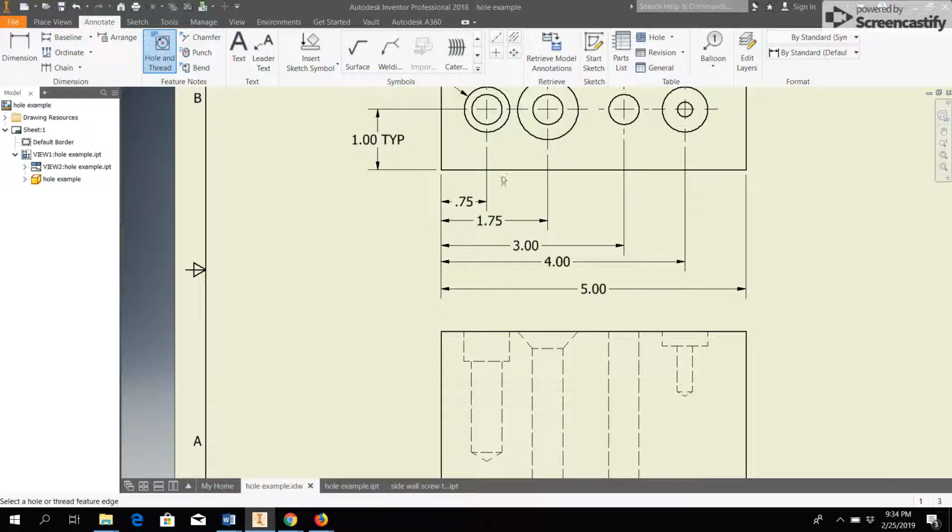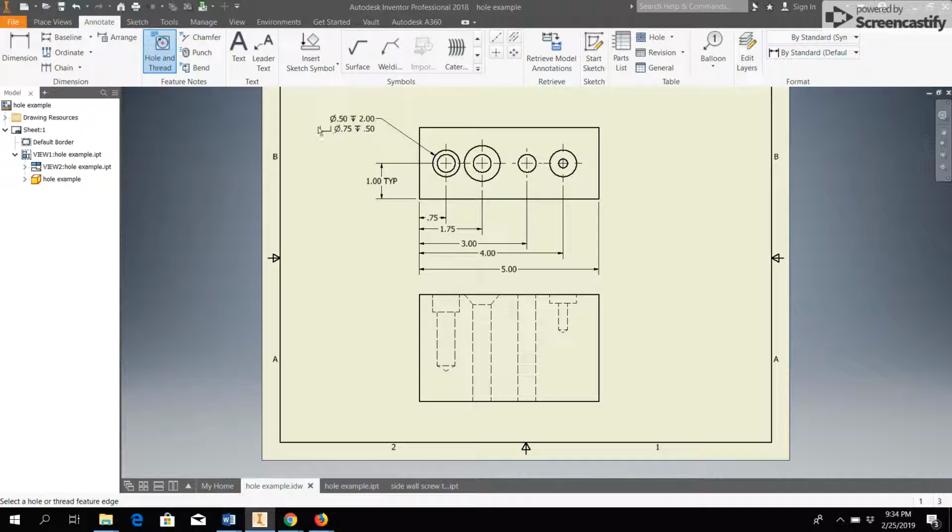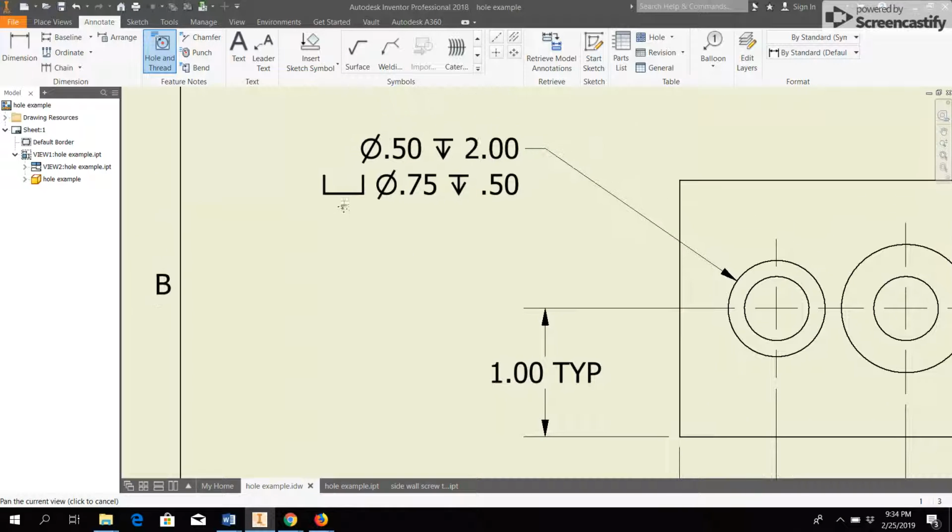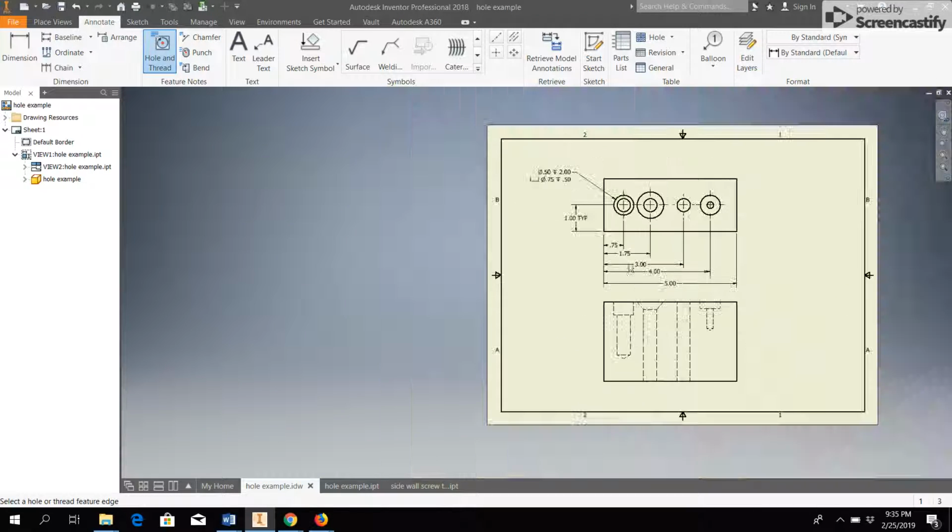You can see then that it starts with 1 diameter, this bigger diameter here, and then it goes to a narrower diameter. And that wider part has a lesser depth. And so that's what this is. This symbol here, the kind of half rectangle there, that tells us it's a counterbore. This is the diameter of the counterbore, the wider part, and this is the depth of that larger diameter portion. The 2 inches is the total depth of the hole.